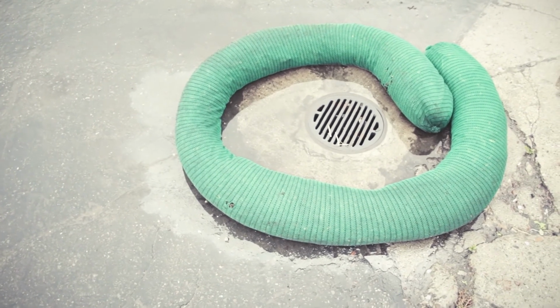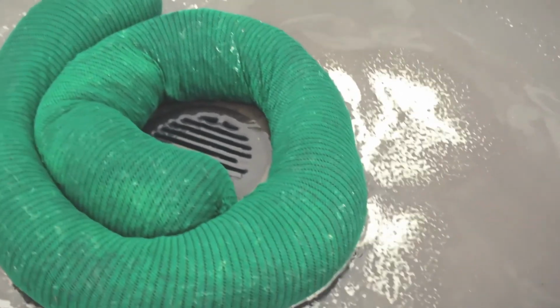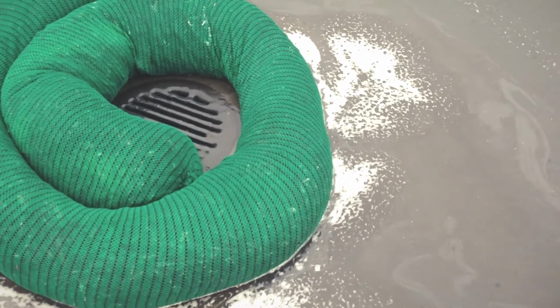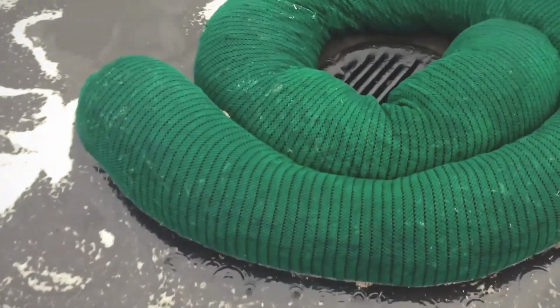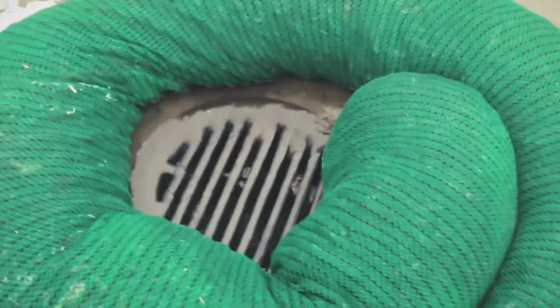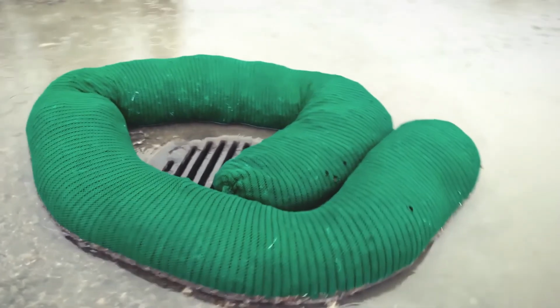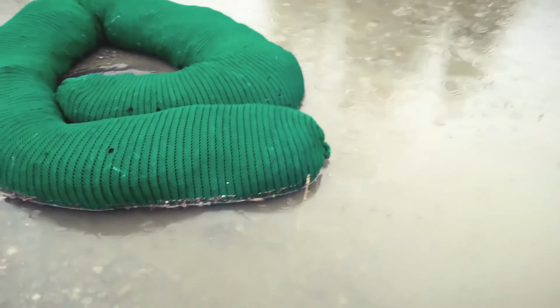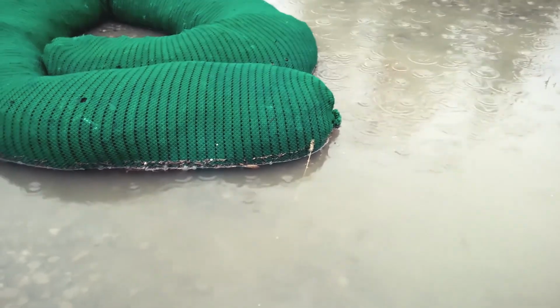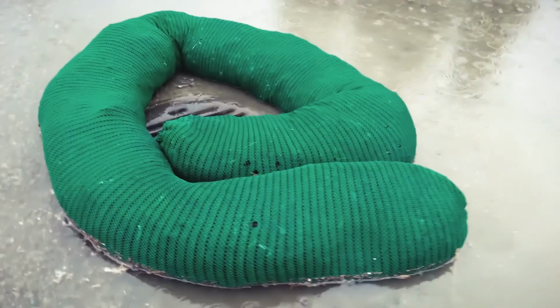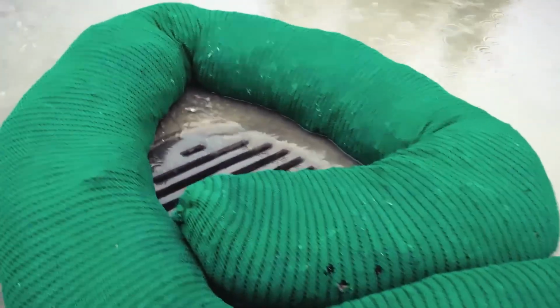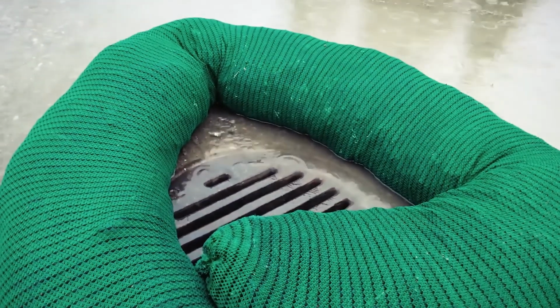So, while these results may seem pretty extreme, we actually have documented several projects with results very similar to our experiment. In the weeks since performing this experiment, we've had guys out in the field send us video of fiber roll performing exactly like we saw here in this gravel lot. So it looks like compost filter socks are the way to go for sedimentation control and drain inlet filtration. Fiber roll just can't compete with the efficiency of compost socks. And given the fact that compost socks usually last much longer than fiber roll, the price difference is pretty minimal.